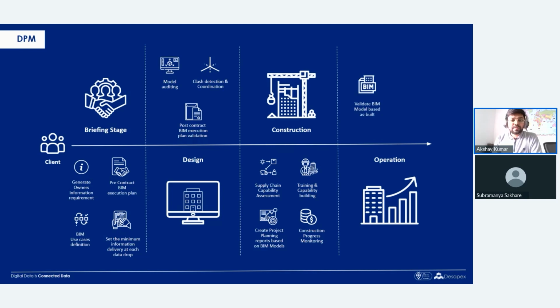During construction, we use AR and LiDAR scanners for rigorous construction and progress monitoring to help owners keep their project status in check and meet the desired quality and timeline. Once constructed, we support the owner with accurate as-built validation using LiDAR scanners and model upgrades. We hand over takeover documents embedded with BIM models to softly land the project into the operations phase.